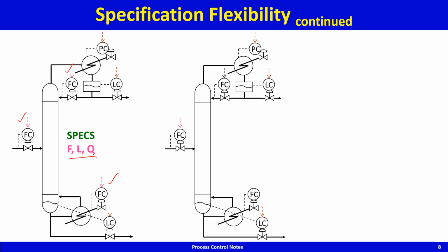Here, same control structure, but now we start adding on top of it. So what I'm now doing is keeping the reflux in ratio with the feed. So I have L by F here, set point specified, and adjusting the reboiler duty to hold a tray temperature. So I have a temperature set point here. So the specs here are this guy, and this guy, and that's exactly. And this S here denotes a stripping tray. So for this control structure, the specification set is this.